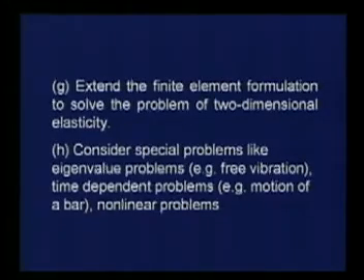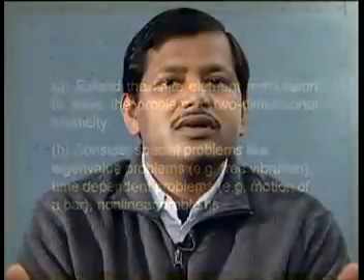Now, once we have finished the two-dimensional problem, then we'll look at certain other special problems which are very important to an engineer. For example, we may be interested in the free vibration problem of a continuous system, beam vibration for example, which is nothing but an eigenvalue problem. Or we'll be interested in the dynamic response of a bar or a beam or a plate under the action of time varying loads. Then we'll have to develop the formulation for a time dependent problem.